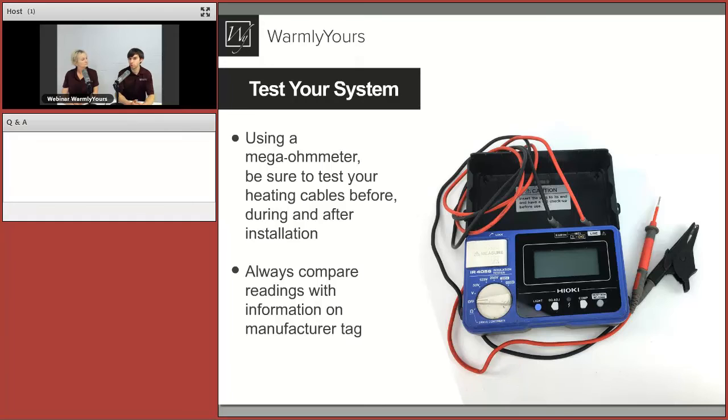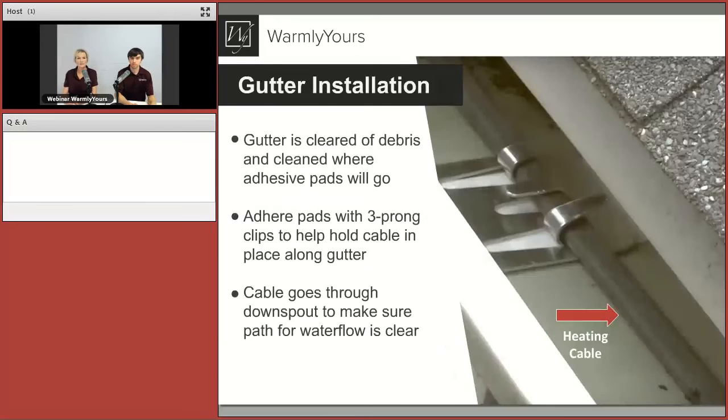You would just test the insulation of the cable. You would run the test between the ground and the internal core, the bus wires, and this way you just know the cable is not damaged throughout. It doesn't have any short, and you're good to go with the installation. Excellent. So always test, guys.